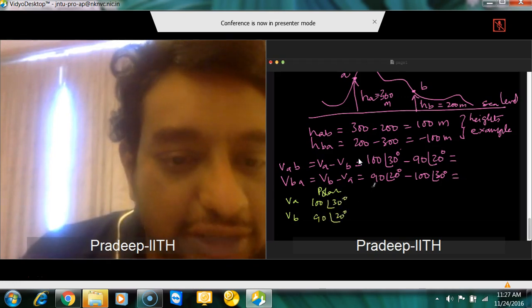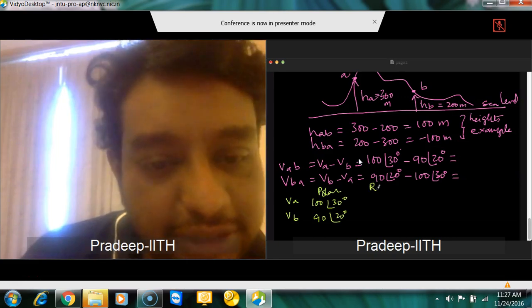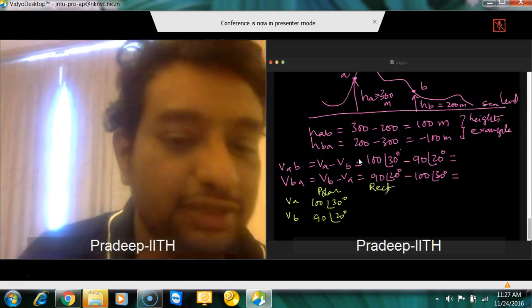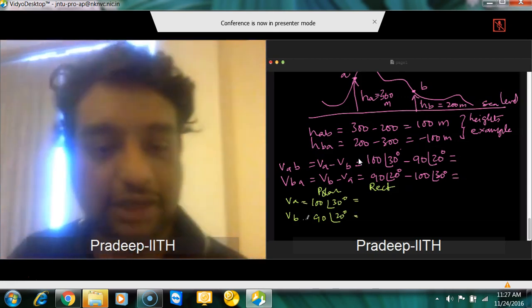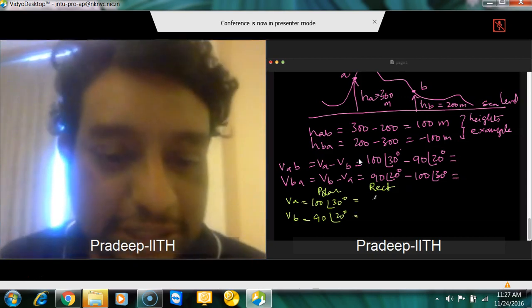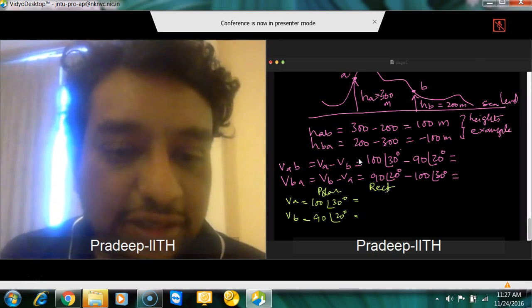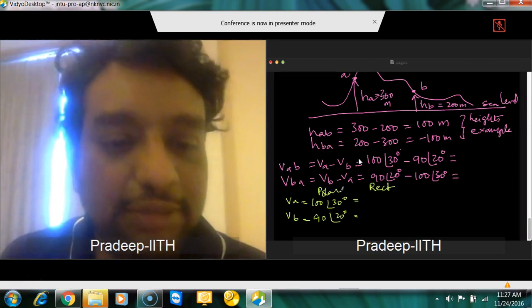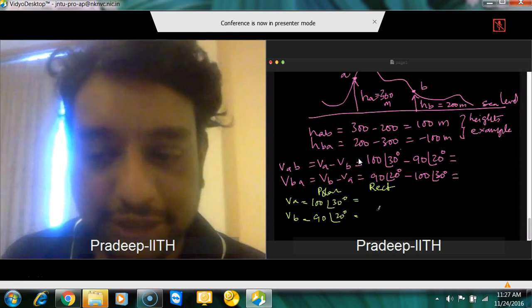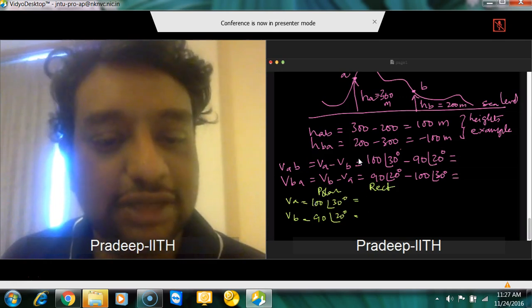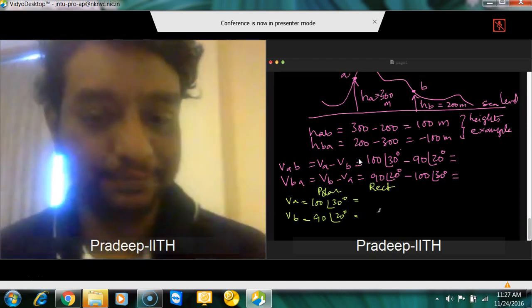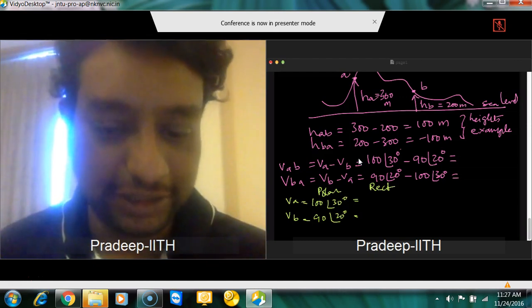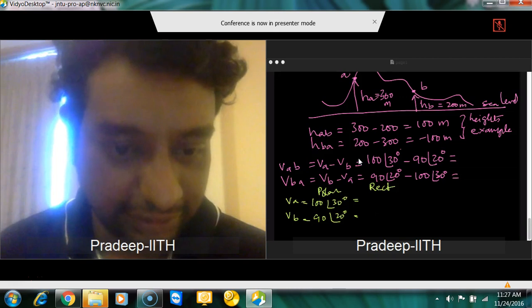So what is the Cartesian representation or rectangular notation? Very quickly we'll calculate that, because for addition and subtraction, rectangular form is better, and for multiplication and division, polar form is better. So let's convert this 100 angle 30 degrees into rectangular form. For doing that, I again switch to the calculator.